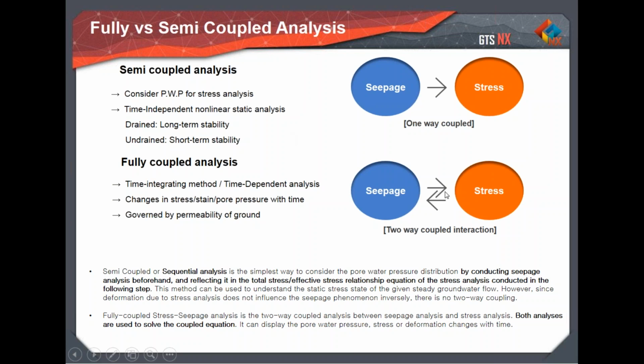However, in the fully coupled analysis, both are considered in a single stage at the same time. So any changes in compression of the soil that forces water out will be reflected, and vice versa. If there's an additional suction created, or some other boundary condition related to seepage, it will be directly reflected in the stress. And this is done over the same time-dependent analysis. So that is the main difference between these 2 kinds of analyses.